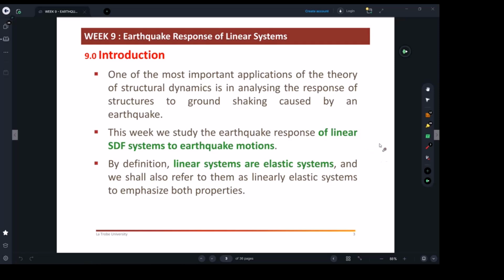So the process we will be applying will be based on the assumption that the system will be vibrating within a linear elastic range. That's basically what we're calling the analysis we're going to be doing, from which we're going to develop the spectral curves. They will be based on assuming the structures are elastic, vibrating within that linear behavior of any structure.